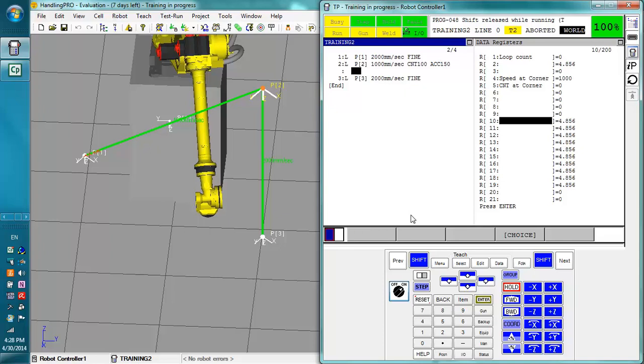One thing I should mention about using a higher acceleration is that you will definitely decrease the lifespan of the robot motors because you are overclocking them, and it does increase the chance of an overcurrent alarm. Overcurrent alarms will require rebooting the robot, so that will definitely interfere with cycle time because you're going to have to stop the robot, stop production, restart the robot, get it back to home position, and start it all over. So this is something to take into consideration. Just be aware of it. If you're having overcurrent issues, then you should lower your acceleration back to a normal value.